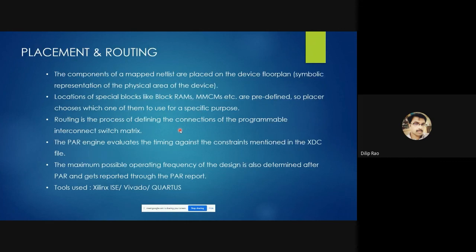Placement and routing is a crucial part which decides how quick or how efficient your design can perform. It is going to consume an implemented netlist, and then place each and every mapped component physically onto the device structure. That's the functionality of the placement tool. The idea is it's going to select the essential hard blocks according to your constraints.